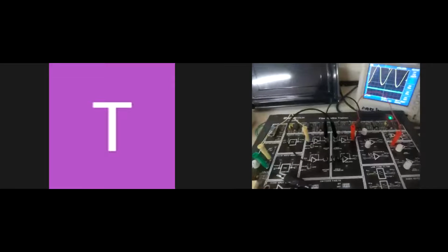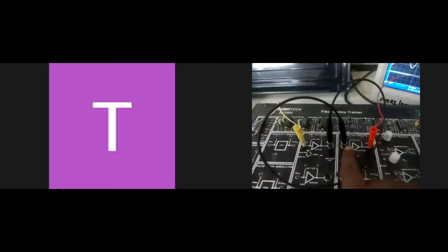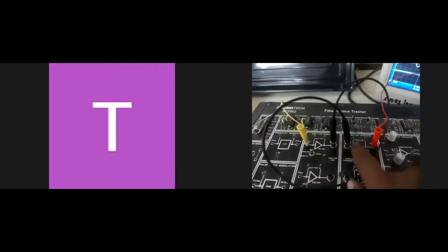So this is our basic input signal, the basic analog signal which we transmitted, as we saw. Now this analog signal is in electrical form here. It goes here, still here also it will be in electrical form. Here it is converted in the form of light through this LED. Again here it is also in the form of light, but through this detector.